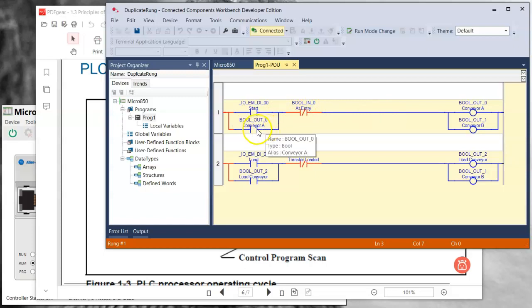That's a little bit redundant. You could just pick one, but I picked conveyor A here to latch it in. Since conveyor B was in parallel, anytime A is on, B would have to be on, right? So when we put the start switch on, and the photo eye condition was true, we can pass through and turn on conveyors A and B until the box reached the photo eye.